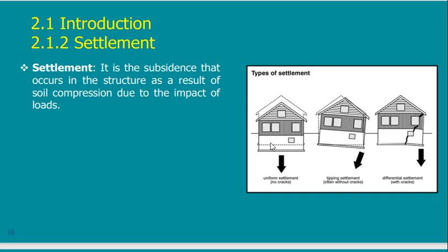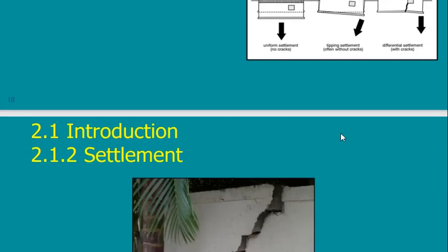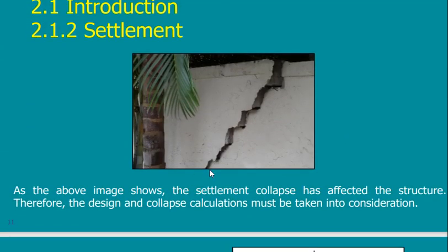Either I would be very lucky and my building will settle as one piece, or one block, or I have the building tilting because the settlement from one side is bigger than the other, like the Pisa Tower, or I would be in a very bad condition because the building suffered lots of differential settlement and ends up with cracks all over the building. So these are important. This is a similar case for a big crack in a wall because of settlement.